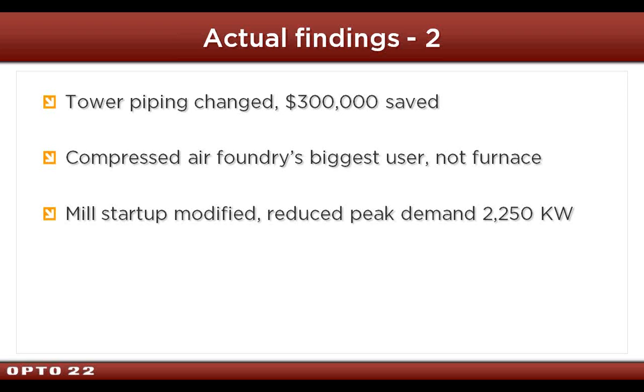We went in and instrumented the plant, and we found out their electric furnace was not the bigger user. It was compressed air, and it was horrible. They were wasting huge amounts of compressed air. Compressed air, every place we've ever been, is a huge opportunity for savings. Made some changes, shut some stuff down. I don't know if they ever spent any money, and it cut like a third off their compressed air.